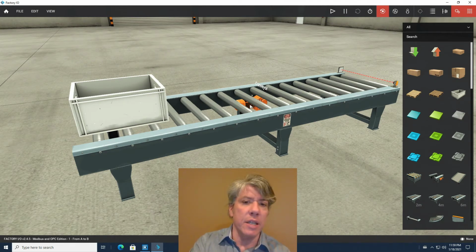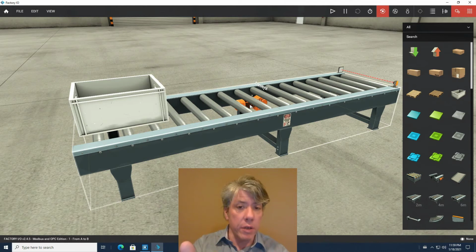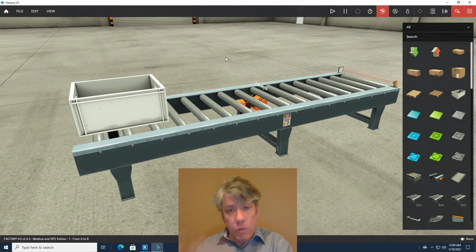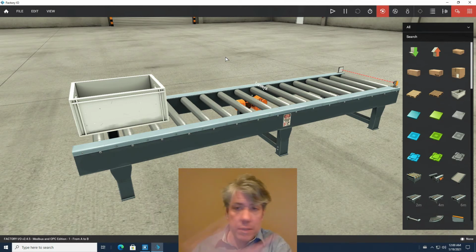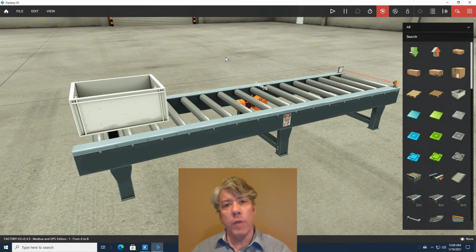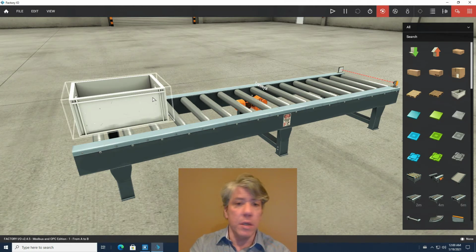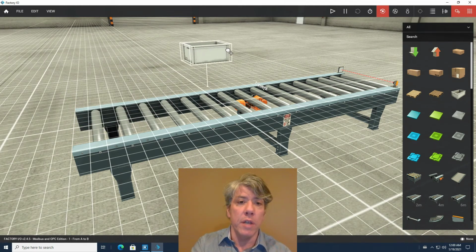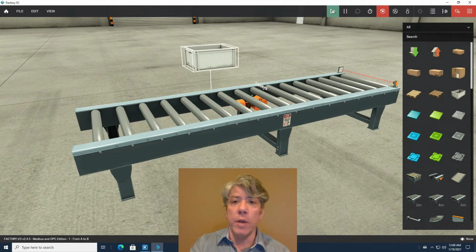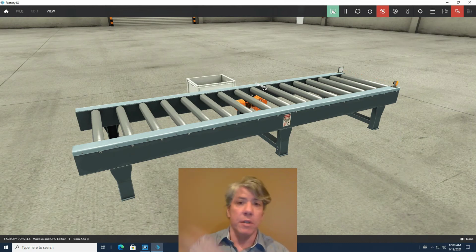You can look at this and see this little conveyor motor under here that the PLC can turn on and off. Now, it's not a virtual PLC, it's the real PLC sitting there. Right now it's sitting on the floor in that lab, and what it will do is send a command to this software, if you program it right, to turn on that motor, and you'll see this tote start moving down the line. Now, this program simulates some physics as well. You can grab a hold of this and move it off, and then when you hit play and you start simulating it, it falls to the floor.